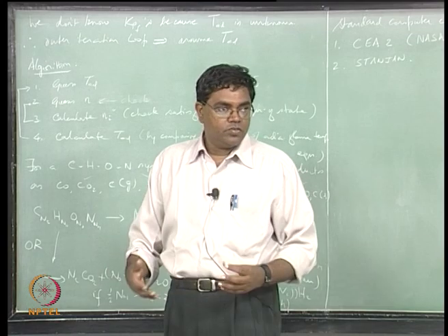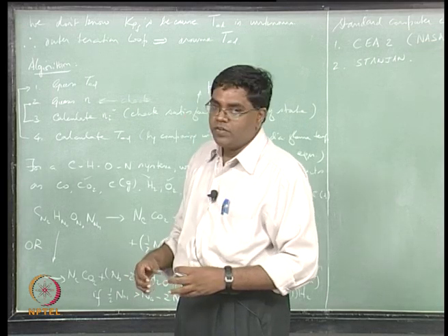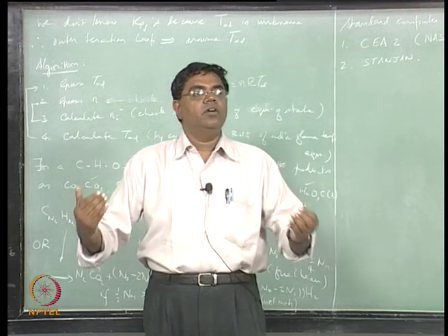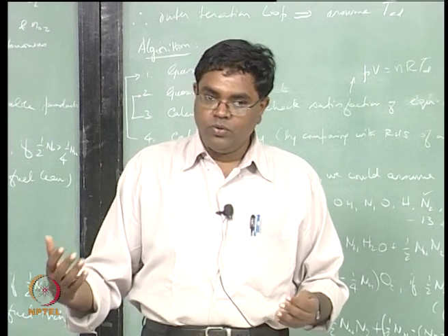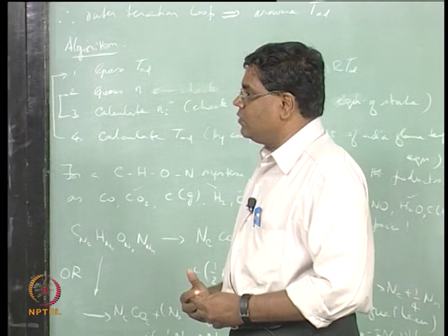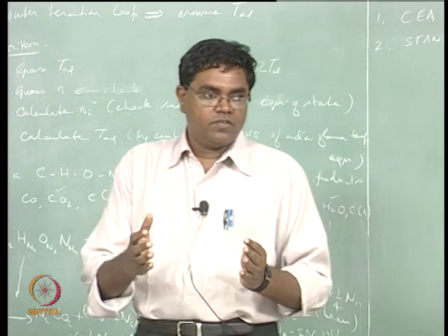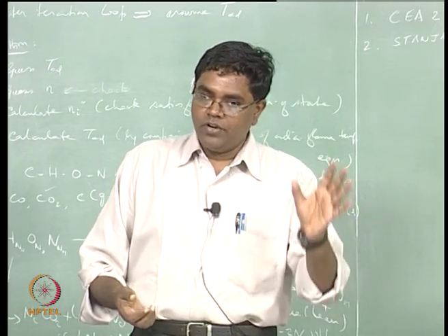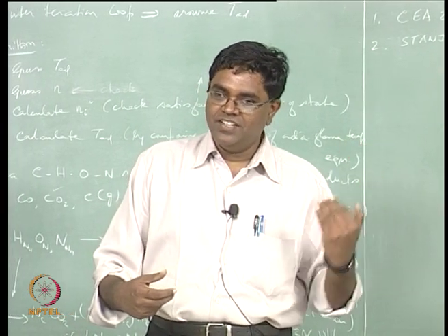will be uploaded, so that we can go through numbers. Let's say you now throw in some CP data like polynomial fits, or make an assumption of a calorically perfect gas and say constant CP, but you need to look at typical numbers for these and so on. We can do this, and in fact I can also show you, if you assume only the standard products, like let's say you take methane plus oxygen giving carbon dioxide and water, we can go through that calculation and you will find that the temperature is actually shooting up beyond about 3000 Kelvin.